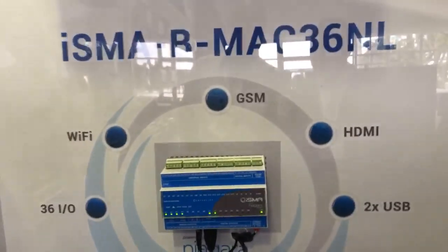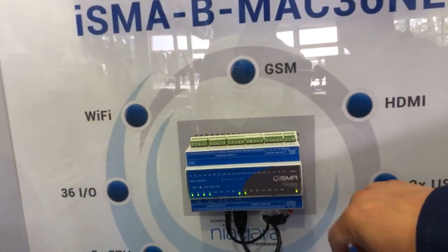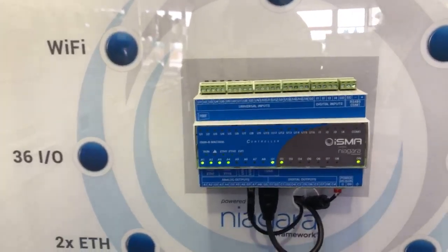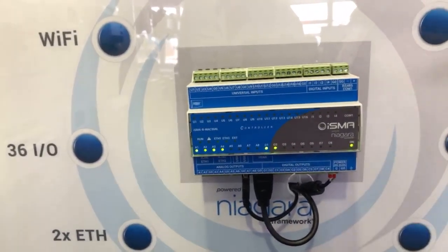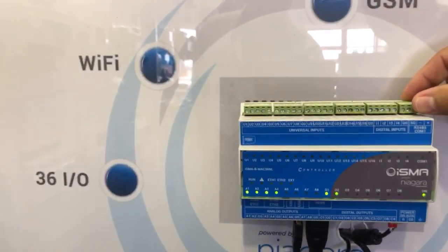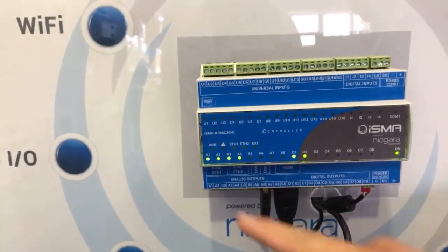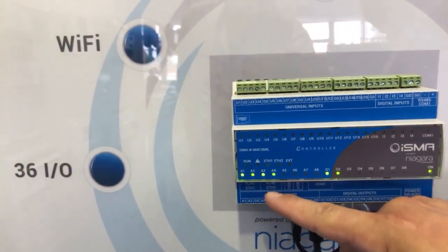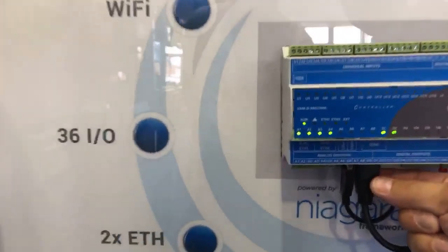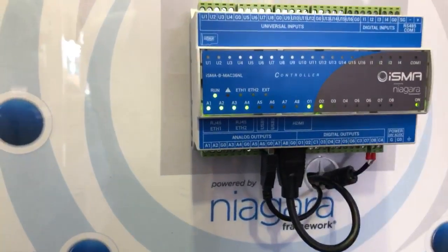So that's the Mach 36A. It's a master application controller, powered by the Niagara framework, as you can see here. Niagara 4.6 and 4.7 are available right now. It's got 36 inputs and outputs on the board, RS-485 here, and an option for another RS-485 on the bottom. Two independent IP interfaces, and the unique function we want to show you right now is a built-in HDMI with USB, which controls the touch of the display.